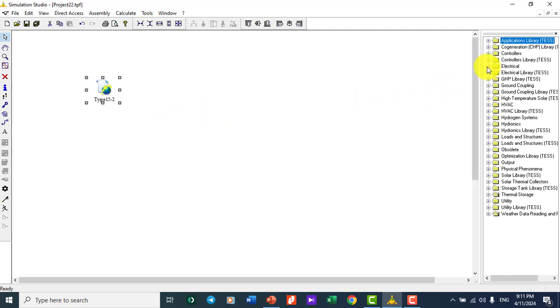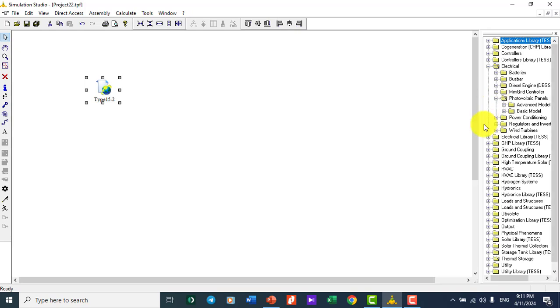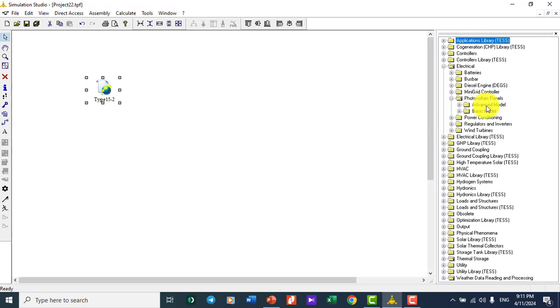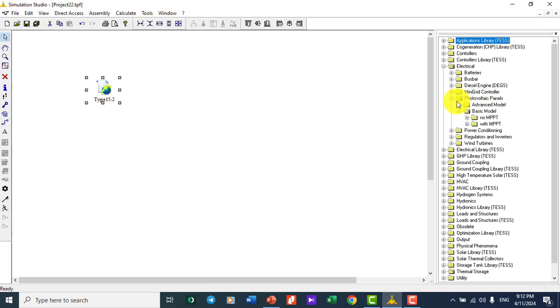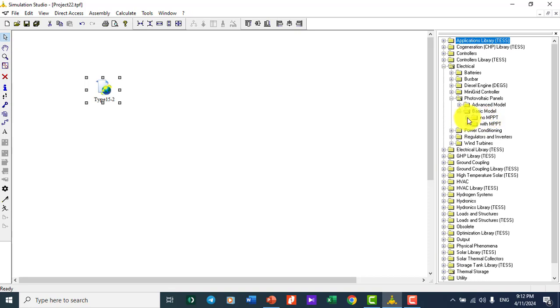If I go to electrical here, then all the way down to photovoltaic panels, I have advanced option and basic model. I just want to use the basic model here. Let me check it. I want to show you with no MPPT, because in other videos I told you how to use that.